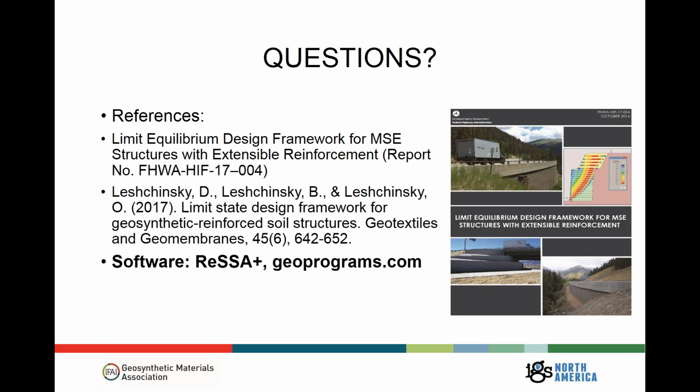That's a great question. It's actually one of the limitations of a limit equilibrium approach: we're really talking about the strength limit state, and that problem is more of a service limit state condition. Whenever there's compaction in the backfill, especially near the facing, there's some residual loading left over in a reinforcement. Whenever there's uneven settlement, particularly between the stiff column of blocks or facing units and the reinforced soil, you might have a parasitic load that appears at the facing.